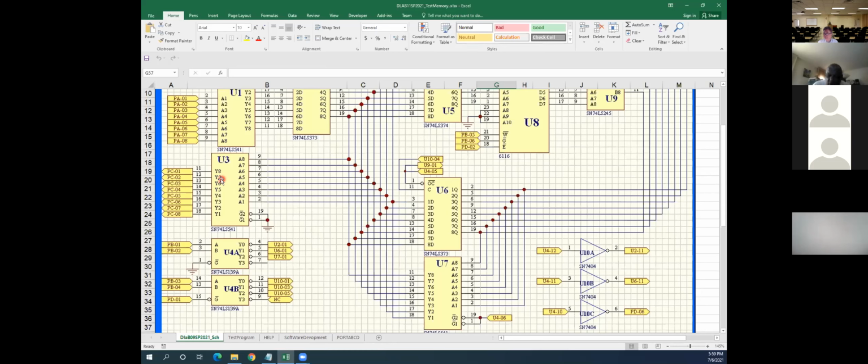In order to read data from memory, the first thing you have to tell is which address. Okay? Then you can set it up to read. Again, pin 21 must be 1, pin 20 must be 0, pin 18 must be 0. Then the data comes out. Those are just the opposite of writing, correct, Mr. Pham?